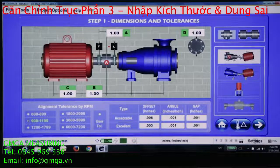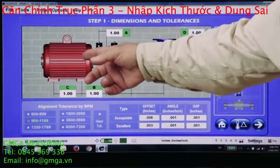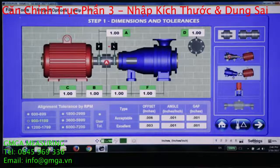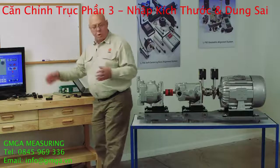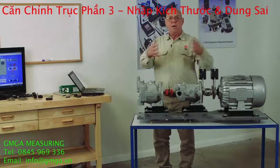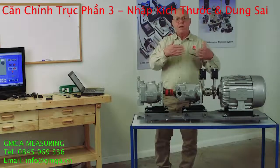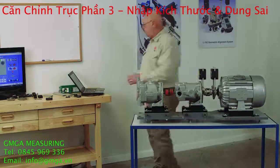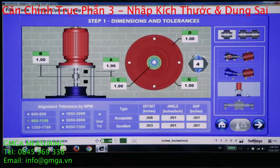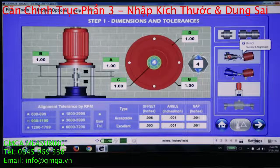This is our standard alignment. In other words, this is fixed. This is our movable unit. If I had a bolt-bound unit, I could select bolt-bound, and then I have to give dimensions for both units, and then it'll give me the option. I can unlock some feet and lock other feet and find the easiest alignment possible. Okay, we also have a vertical shaft option. These are all options that come with the 680 system.